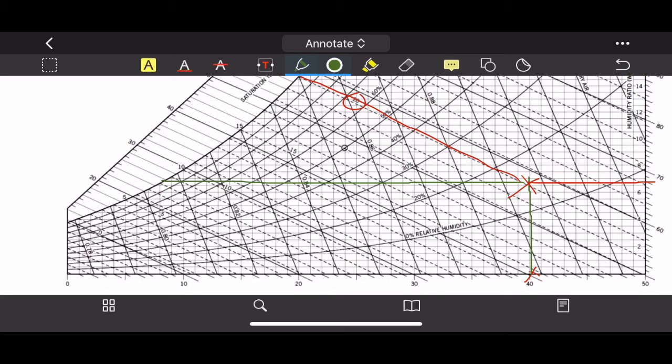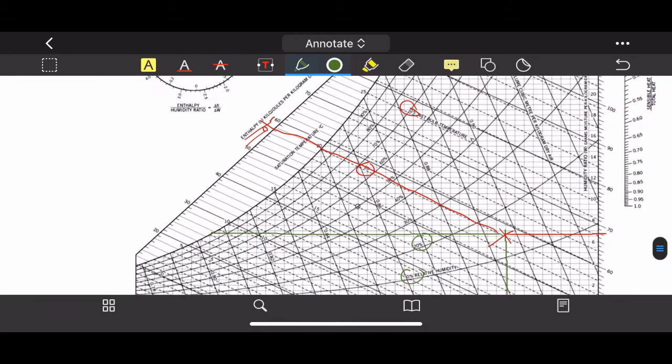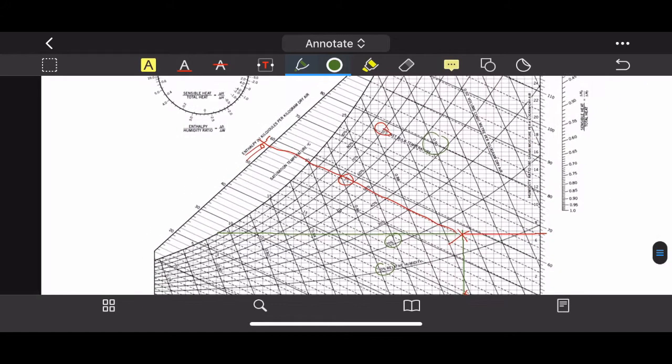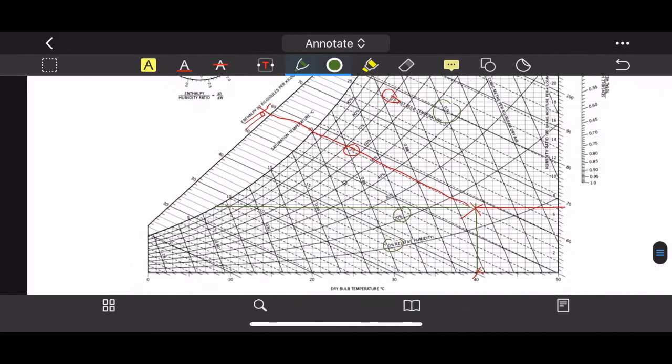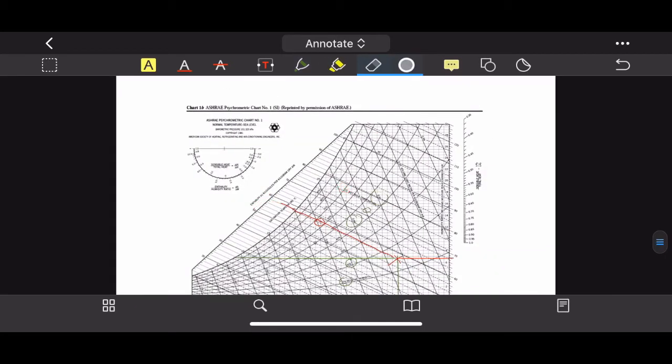Relative humidity is this line. Relative humidity is this curvy line, which is between 10 and 20%. So on my answer there, I put 14%. Find the distances, and the specific volume will be this line, right? So it is between 0.9 there and 0.88 there. So between there it should be just 0.89, but it's a little bit above, so it will be around 0.896 as shown in the answer script. Okay, very easy.